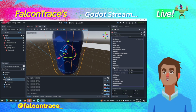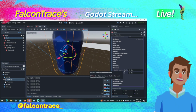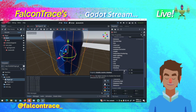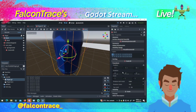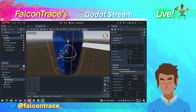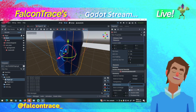Then we have the shadows. From here we can only disable the reception of shadows. If we want to disable this material from projecting shadows, there's another option. I'm going to show you in a second. You go to this part that says geometry, and it says over here cast shadow. You have to set it as off.